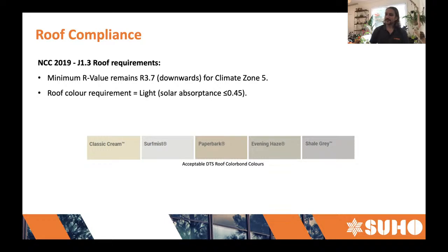Yeah, going back to the noise question in the comments, in terms of geometric thermal bridges, like corners of buildings, we're at this stage not really focusing on that level of detail. It's still very general, as in full facades of a wall type, a ceiling type, a floor type, that sort of thing. And also not touching on things like where hypothetically you might have a concrete floor that is exposed on the outside and effectively allowing heat transfer through, which apparently does have pretty big impacts in terms of thermal bridging as well.